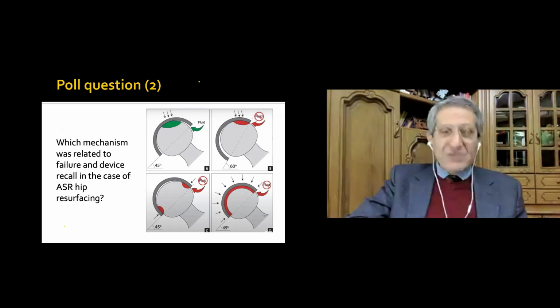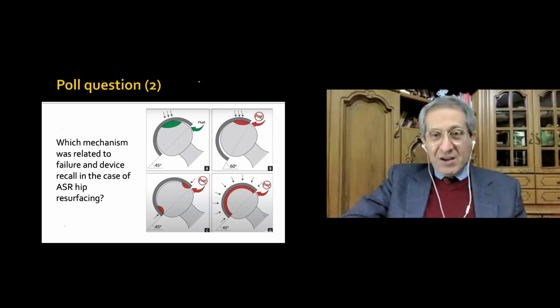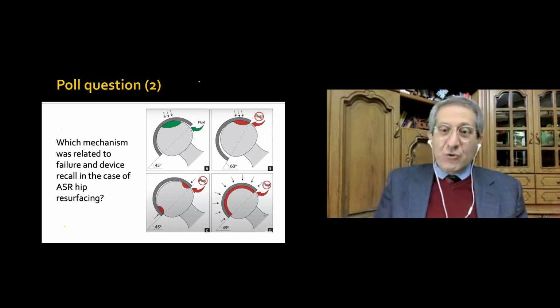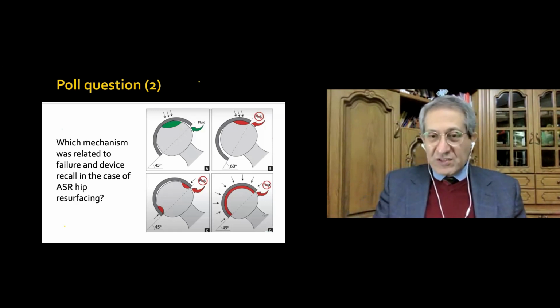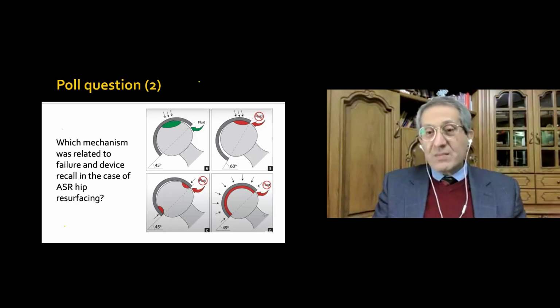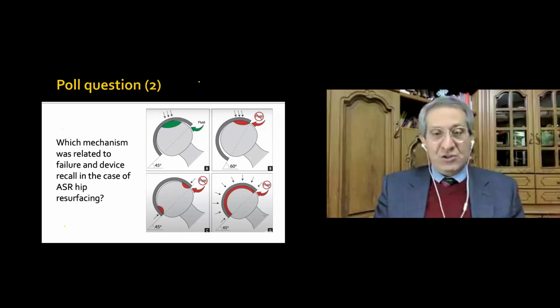The correct answer is B. The ASR acetabular cup had an inside groove against which a surgeon pressed a tool to implant the component. The groove limited the surface area inside the cup. As a result, the ball was more likely to strike the cup's edge, causing wear and generating metallic debris. This was particularly prone to occur when the cup had a more open inclination.